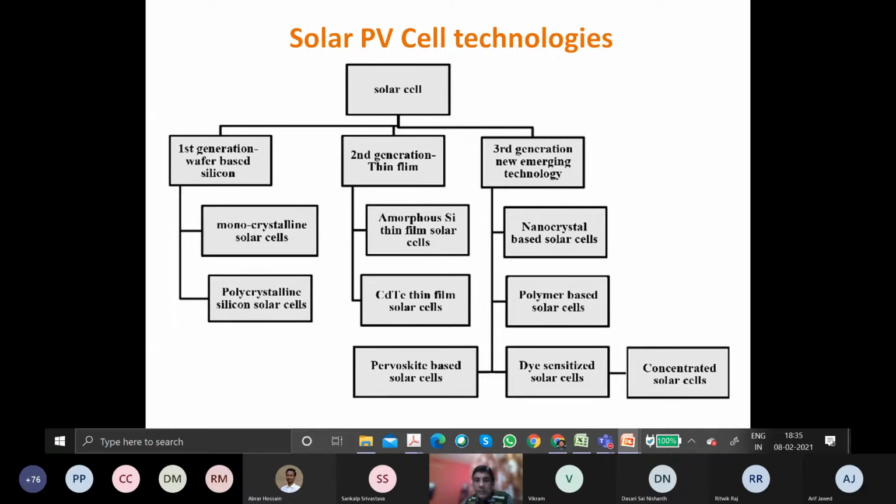Okay, so that is the reason that if you have another material which has a different band gap energy, then it can absorb more photons, or wider energy photons can be absorbed. So overall efficiency will be more. If you can capture more photons with a wider energy band gap, the efficiency of the solar photovoltaic material will be more.